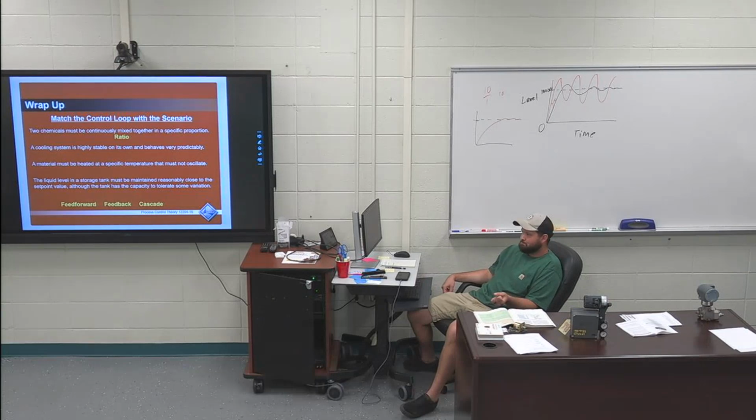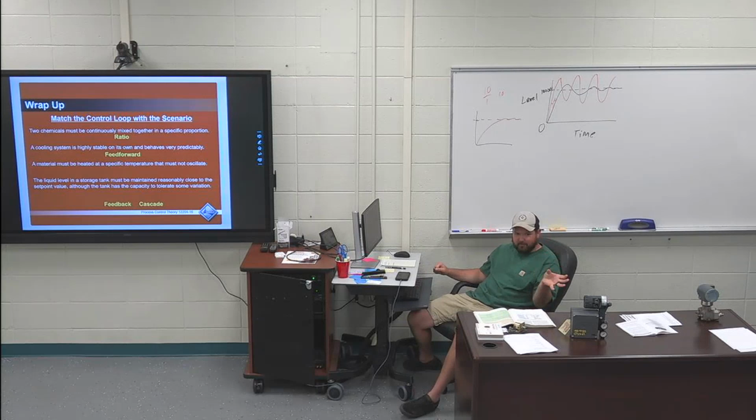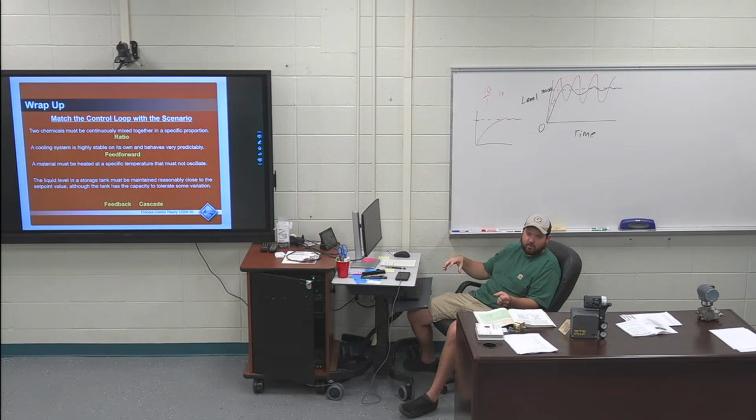Cascade? Feedback? Nope. It's going to be feed forward. So if it behaves very predictably on its own and it's highly stable, I don't need to control it that much, right? It's like you opened up that valve a little bit and you just set that output to that valve, however open or closed you want it to be.